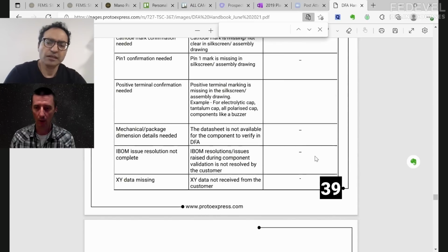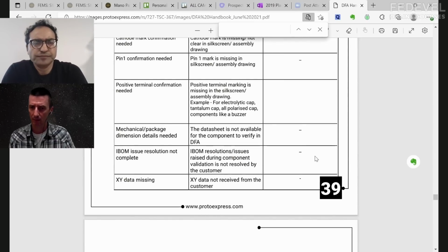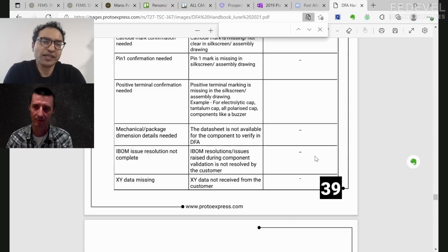So what can be the factors? Because this can help engineers again to design maybe more cost-effective boards for assembly. Because I guess you probably charge more if you do it twice, or it's the same price? If you have one-sided assembly versus two-sided assembly, that's where we charge. How we build it is not where the charge comes in. If we can optimize the manufacturing, we will, but that's not a benefit to the customer. That's just what we're doing internally. Okay. So if you have components on both sides, you're going to get charged for components on both sides. But still, for example, if it goes to the oven twice, it may be a little bit worse than if it goes there only once?